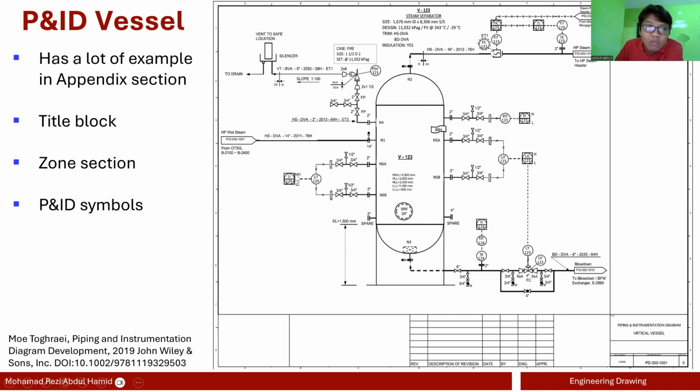LI124 is your control loop number. HH and LL here are a high alarm and a low-low alarm. One important thing for you to note here is that HH is 2800, and then LL is 305.